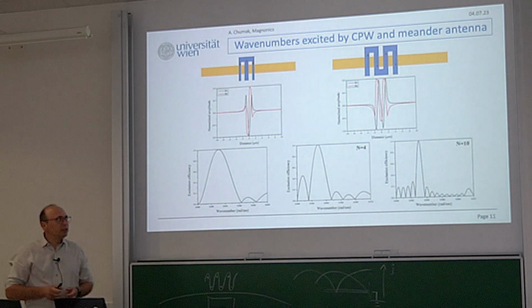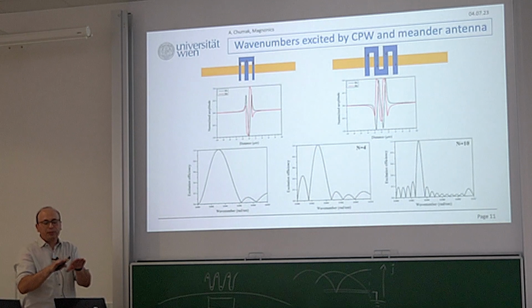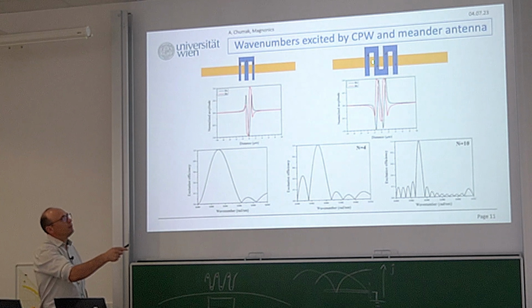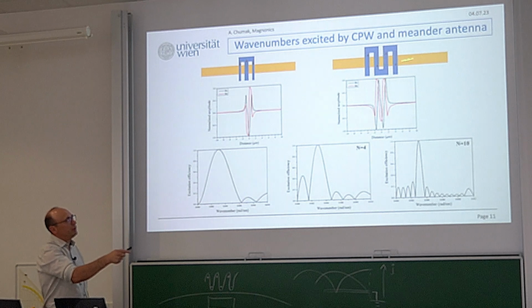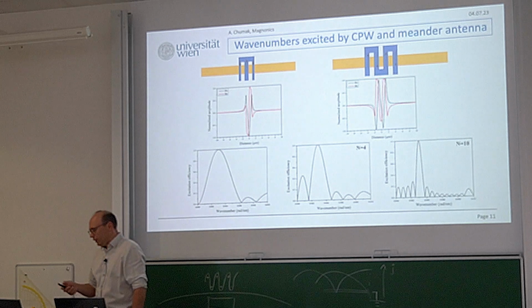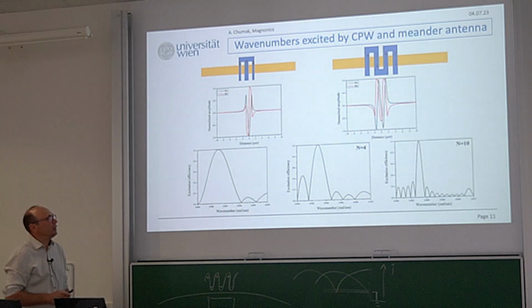Also pay attention that there is electromagnetic leakage here between antennas, and in order to minimize it, of course, these guys will have small electromagnetic leakage because the field created by this antenna at some distance will be compensated by the field created by the nearby antenna. Therefore, CPW meander is a good idea to decrease electromagnetic leakage.